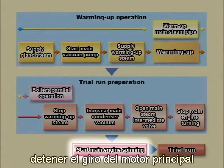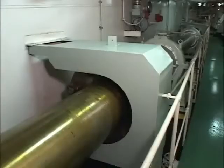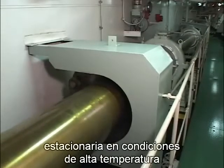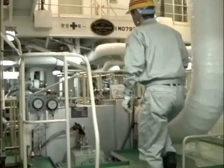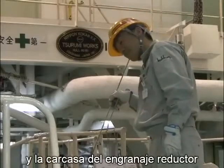Start main engine spinning. Start spinning immediately after main engine turning has stopped. Upon stop of main engine turning, proceed to spinning as quickly as possible so as not to leave the turbine stationary under hot conditions. Once the spinning has begun, use a listening rod to confirm that there is no abnormal sound inside the turbine casings and reduction gear casing.